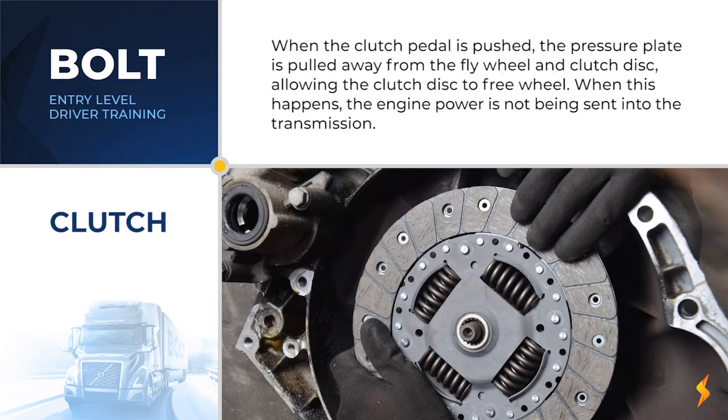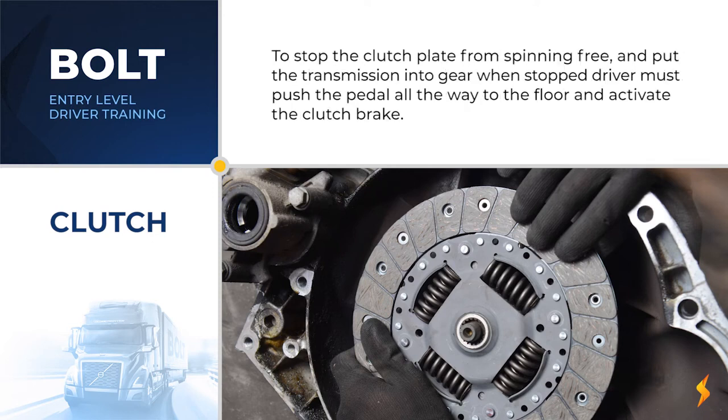When the clutch pedal is pushed, the pressure plate is pulled away from the flywheel and clutch disc, allowing the clutch disc to freewheel. When this happens, the engine power is not being sent into the transmission. To stop the clutch plate from spinning free and put the transmission into gear when stopped, the driver must push the pedal all the way to the floor and activate the clutch brake.